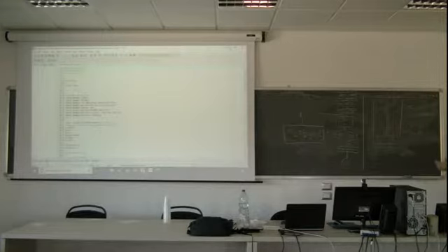Great. So, if you have a solid, for example, or whatever domain, what will be the temperature gradient in this domain, because we are on temperature now? We will experience a lot of gradients because it's a processor with a lot of heat. Then you need a lot of nodes to capture this effect. In a building wall, you don't need a lot of nodes because there are no spectacular heat flows.